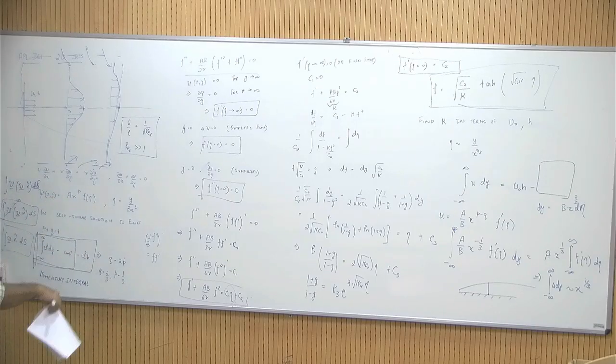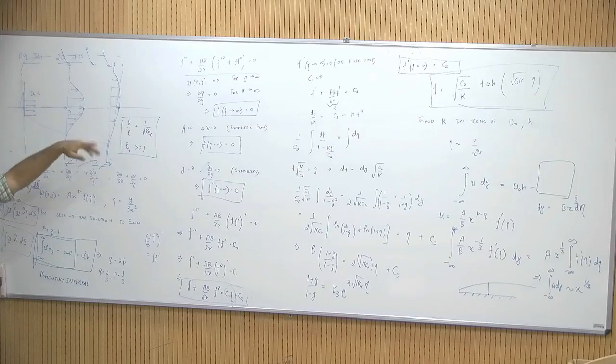There we lose all of our assumptions of continuum and everything else. So how can you entrain more mass if you don't have mass? The jets in vacuum will be totally different. Here what we assumed is that we have a jet of fluid that is coming in, and that same fluid is existing over in the atmosphere. So it is kind of like your submerged jet experiment that you guys have in your labs. You have a jet of air coming inside air.